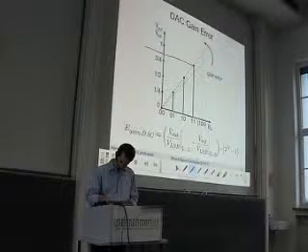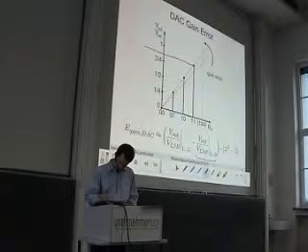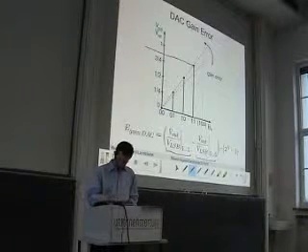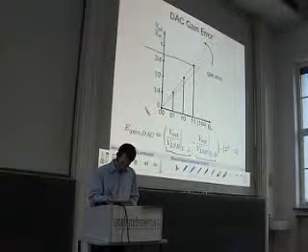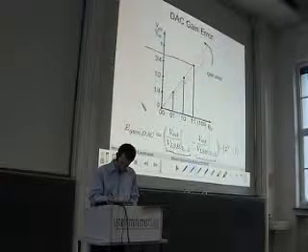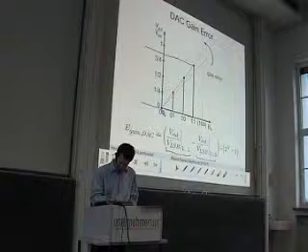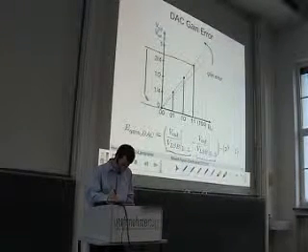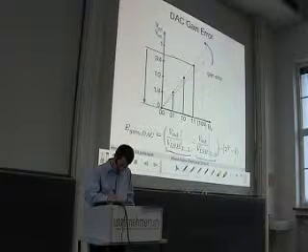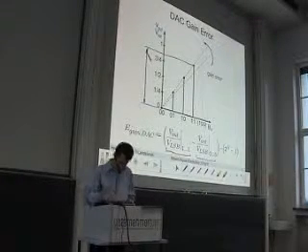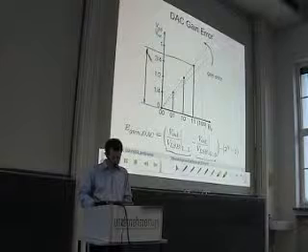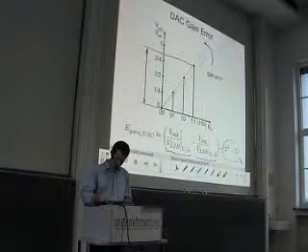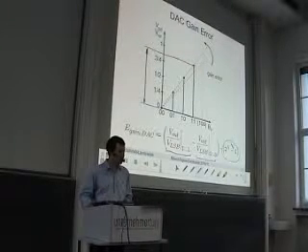The next term is the output voltage for all input bits set to 0. So the difference describes this output voltage difference in terms of VLSB. And we compare this difference to the ideal value here, which is 2 to the power of n minus 1.